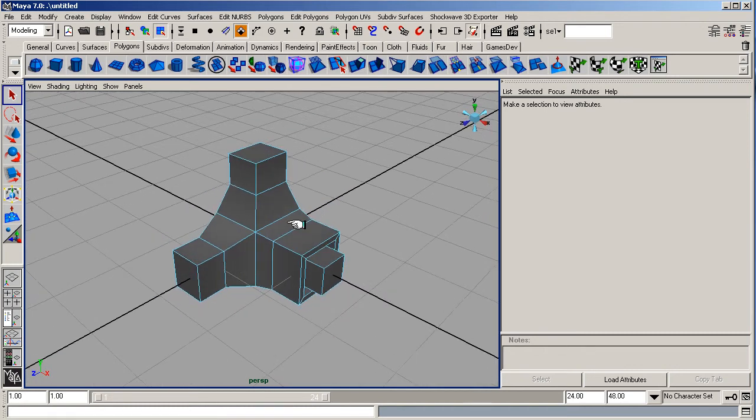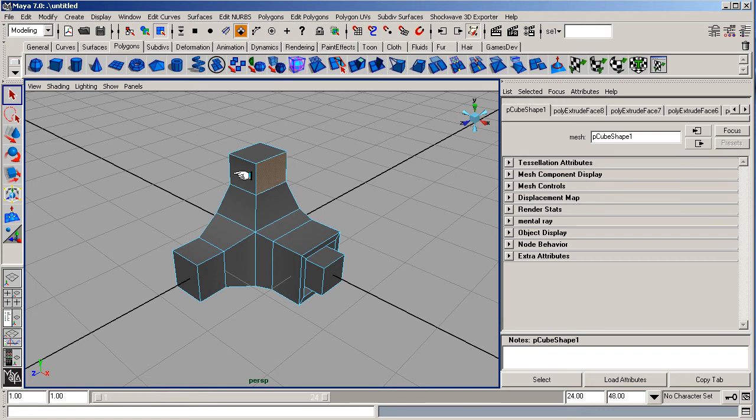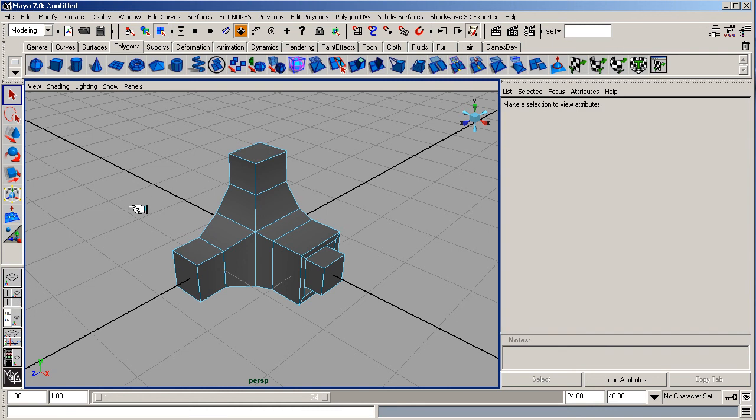Have a play with that, test render those out, see how you get on with that. In the next lesson we'll learn about splitting the polygons and more about polygon modelling. At the moment we're actually not using anything as a reference, but generally you would put an image plane in the back with views, three elevation views, front, side and top, and then you would work your geometry against that and create objects, or you can do it like this and just do it freehand.